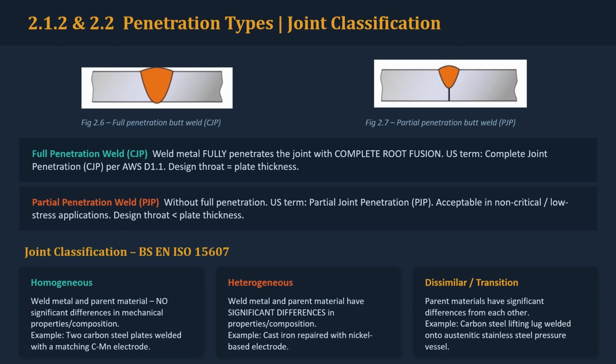The important point for an inspector is that partial penetration is not automatically an unacceptable condition. Whether it is acceptable depends on the design requirements, specification, drawing and applicable welding procedure. The required penetration must be established before the inspection is performed.